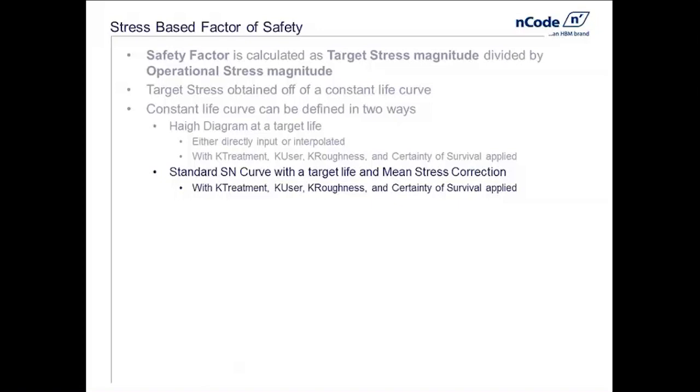And again, the initial SN fatigue curve could be pre-treated, compensated with things such as surface finish or certainty of survival prior to the calculation.